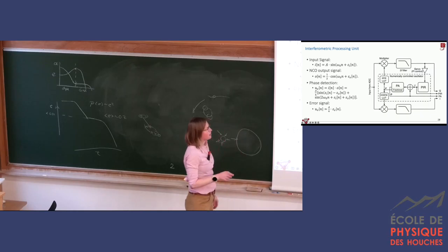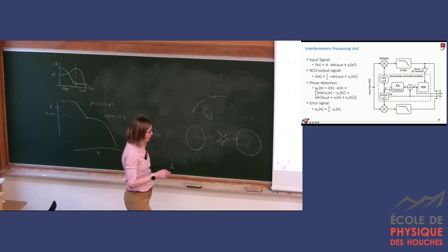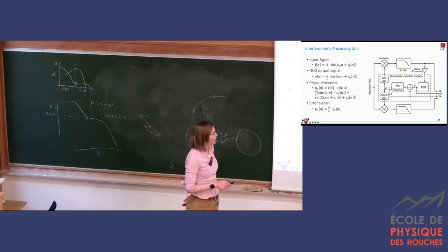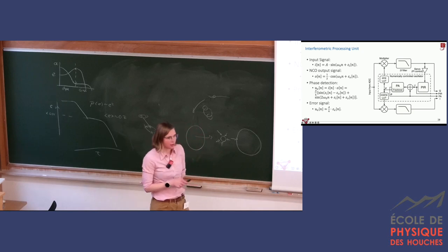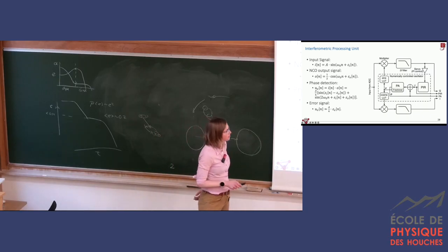So right now, we are in this phasemeter digital land that operates on its own units. Here we have the input signal, and it is multiplied with a sine wave and a cosine wave that are a copy of our signal. So it has the same frequency, but a different instantaneous phase.